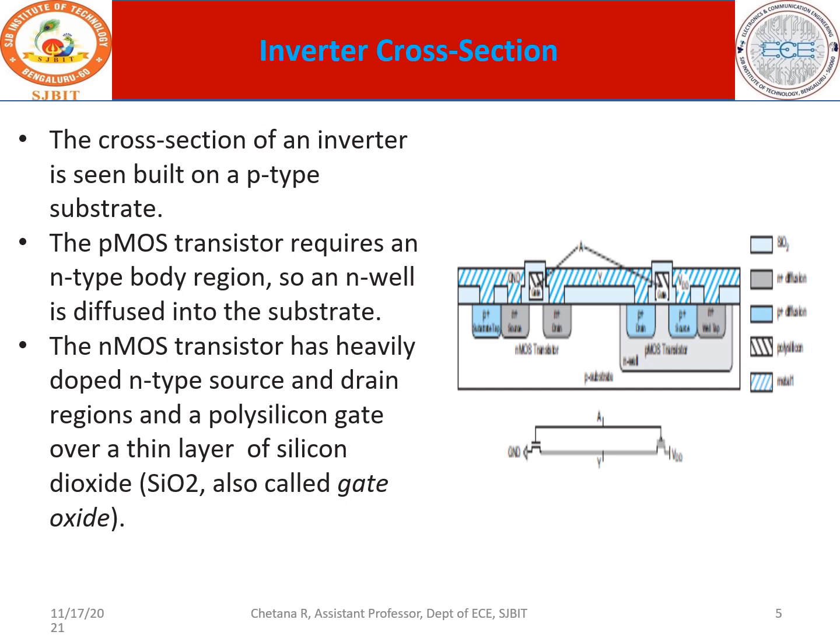But how will you create a PMOS transistor? In order to create a PMOS transistor, you need to have an N substrate, but the available substrate is P-type. So how do you create an N substrate? The N substrate is created by a well structure here. That is what has been discussed here.